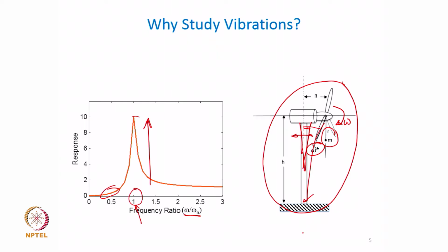So, that is the reason that closeness of the operating speed to the resonance frequencies can cause unexpected failure, untimely, early failures, and that could create problems for us, right. So, in that light, only basing on certain forces and certain operating conditions is not enough, and you need to pay enough attention to the vibration phenomena if you want to make a solid robust design.